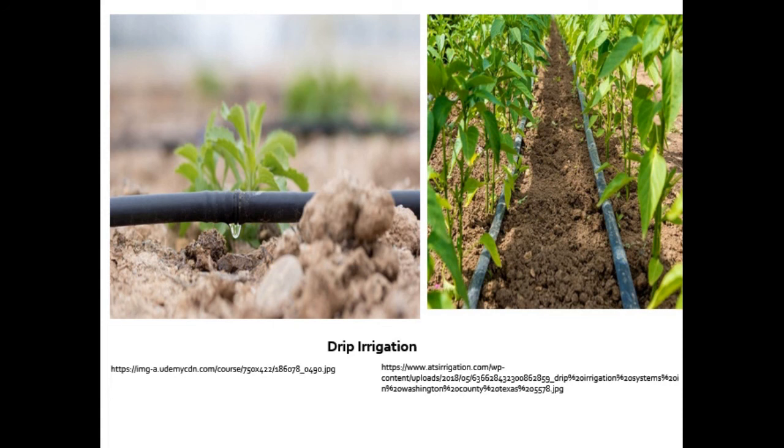This type of irrigation may not be suitable for some crops as salinity can develop, as salt tends to accumulate along the fringes of the wetted surface strip. Likewise, root development may be restricted to the wetted soil volume near each emitter.